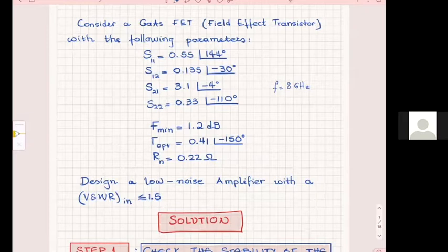Then of course, you have to look at their characteristics, you have to look at the bias, you will have to look at how well your design frequency is situating in the bandwidth of where this transistor performs. You will have to look at the FT to see is it high enough so my transistor works well, all right? So there are a host of other things.